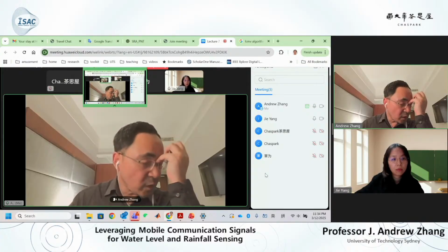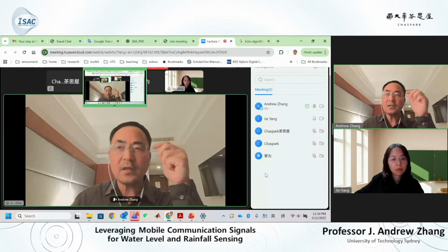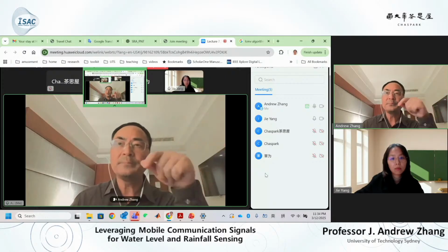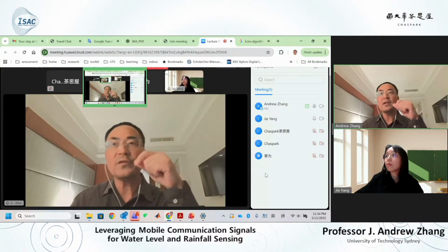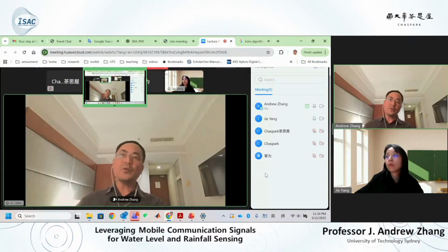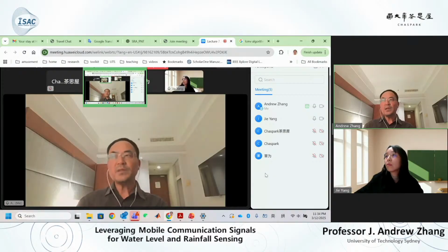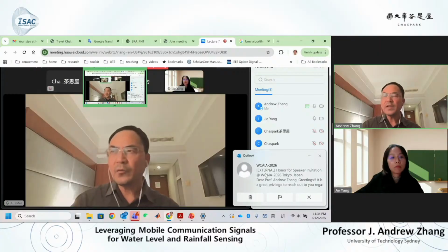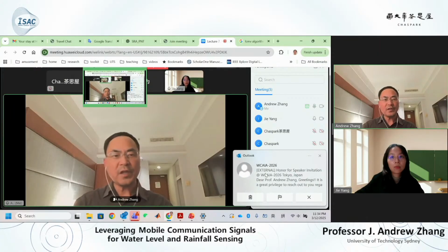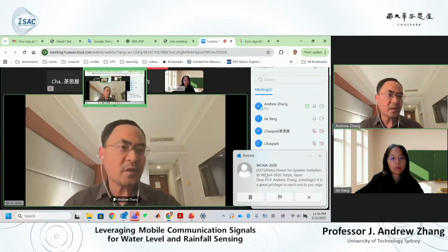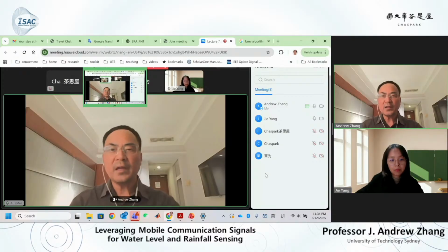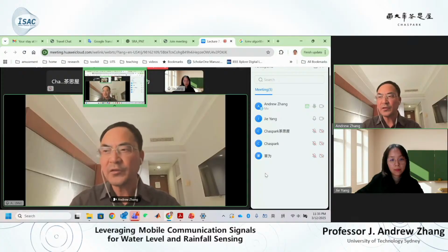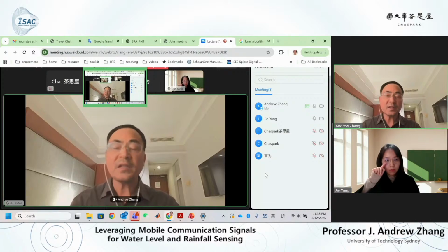The Doppler frequency or the signal variation caused by such movement is typically large compared to the variation caused by water level change, because water level changes at, for example, the minutes level at least, while such dynamics caused by the surrounding environment, wind or passing boats change at a second level.